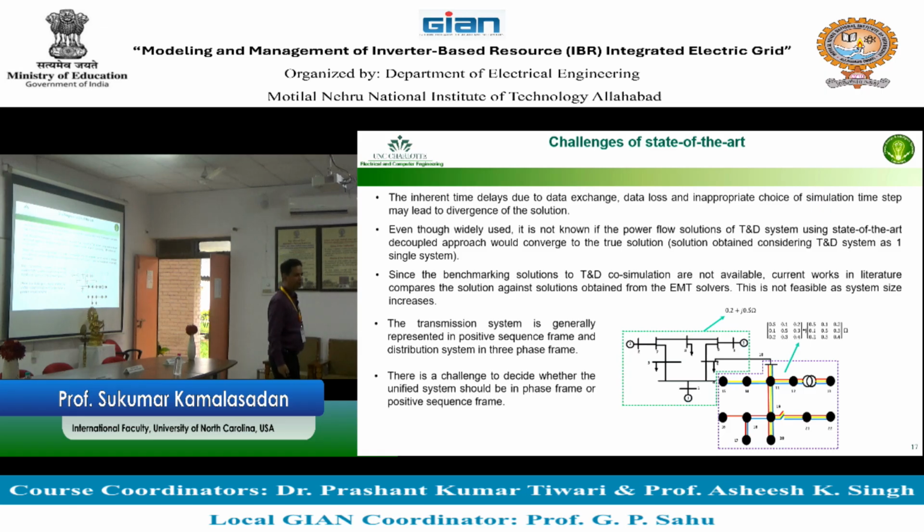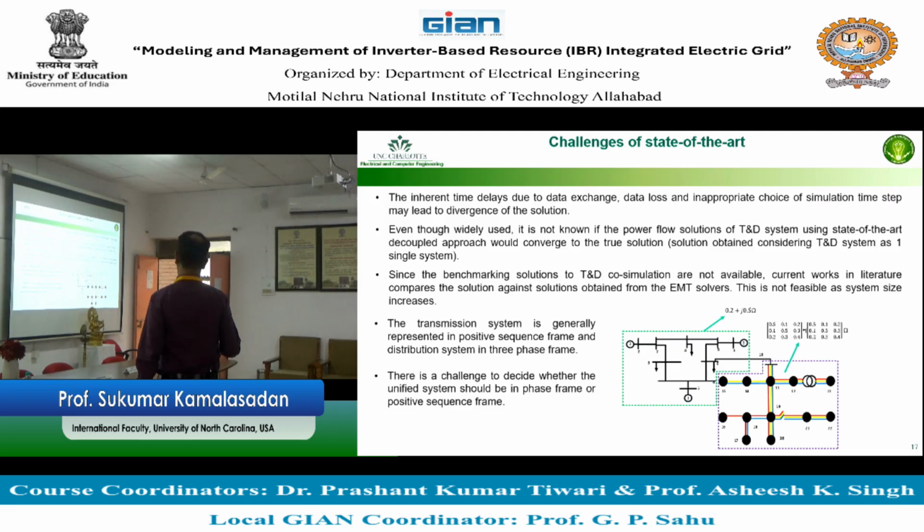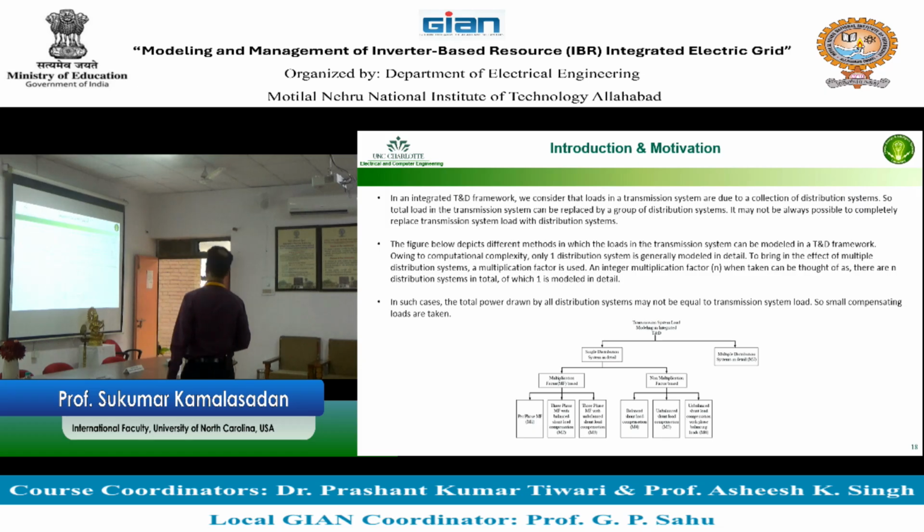Well, the only way to benchmark is to have something completely together, the transmission and distribution system together. If you don't develop something like that, the only place you have is simulation models, in Simulink or an EMT solver, EMT type of simulation. Then only can you actually run it. Otherwise, you cannot run. And the challenge is the three-phase representation versus the sequence representation for the transmission system and phase representation for the distribution.